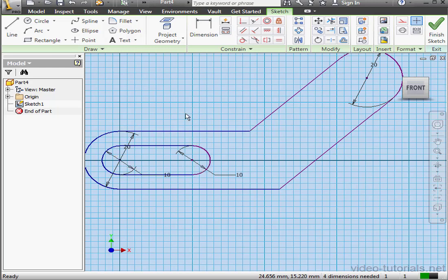them by pressing F9. Now, if you press F8 or F9 and nothing happens, it's because a tool is active. Let me show you what I mean. I've activated the Line tool. Now I press F8, but nothing happens. Let me press Escape on my keyboard to close the tool and press F8 again. And here are my constraints. F9 to hide them.